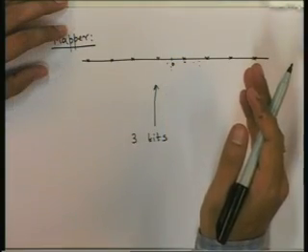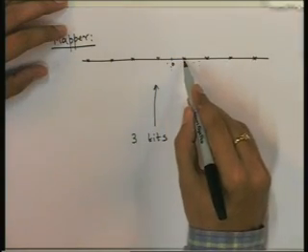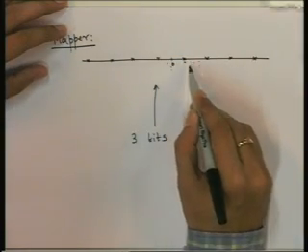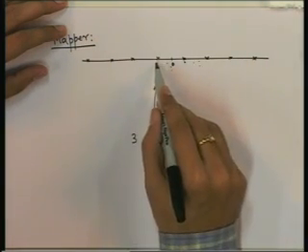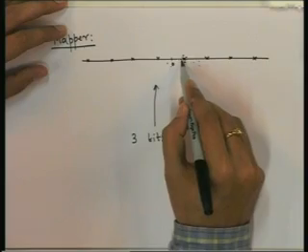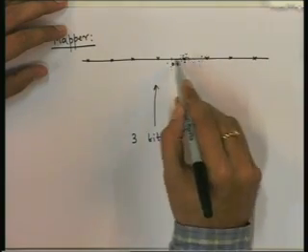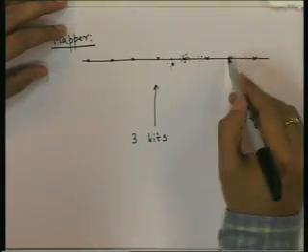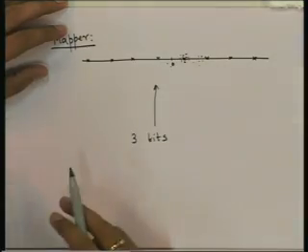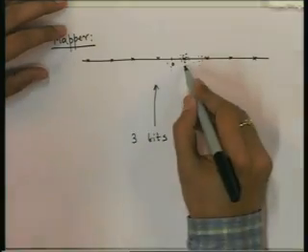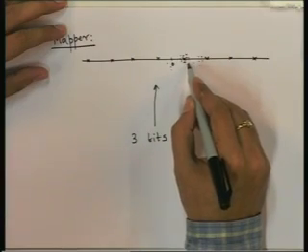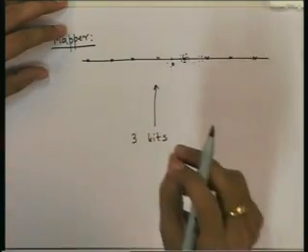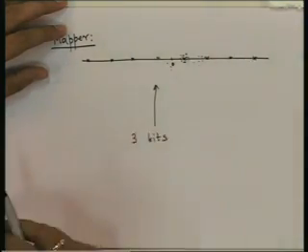There is some non-zero probability of the received point being near the other points, other than the neighbors, but it is a very small probability. Most of the points will be near this itself, but sometimes they will be near a neighbor, and with even less probability they will be near other points. So, when there is an error, most of the errors are because the detected point is one of the neighboring points of the transmitted point.